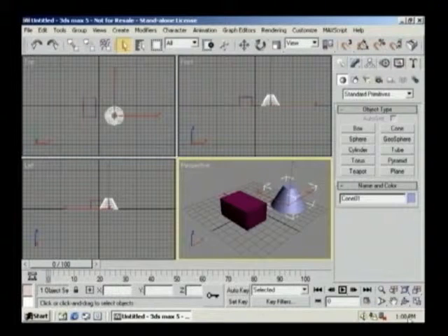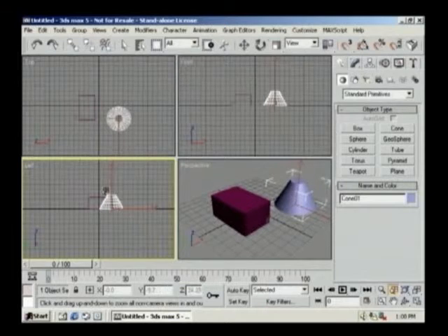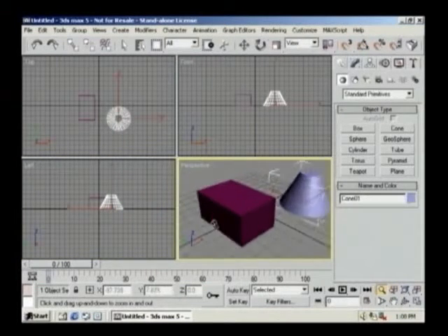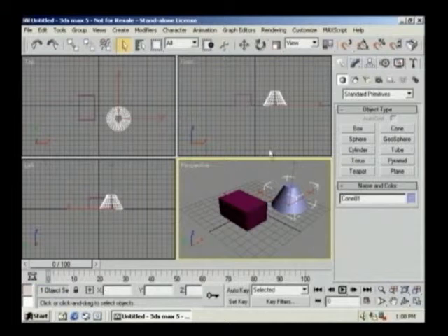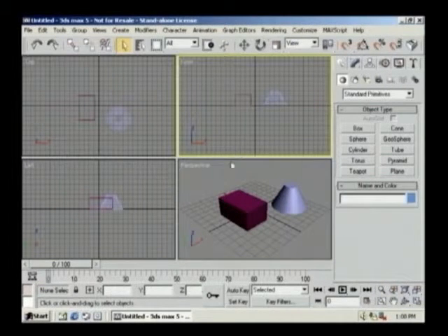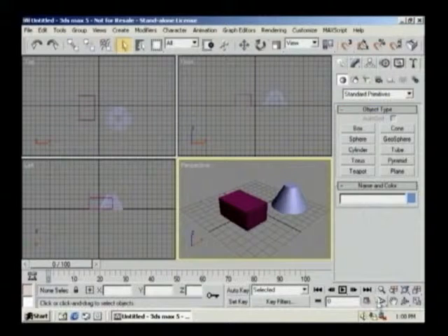And then the lower right corner, these are the final set of tools on the interface. These are your view navigation controls. These buttons allow you to quickly navigate within individual or multiple viewports depending upon what tool you're using. These buttons will change also dependent upon which viewport is active, whether it be perspective, camera, light, top, bottom, and so on. Some of them also have flyouts with further viewing options. If you see this little black triangle in the lower right corner of an icon, this is telling you there's a flyout. And this is also true with any tools, whether it's on the main toolbar or wherever. If you see this little black triangle, that means there are multiple tools associated with that certain tool.